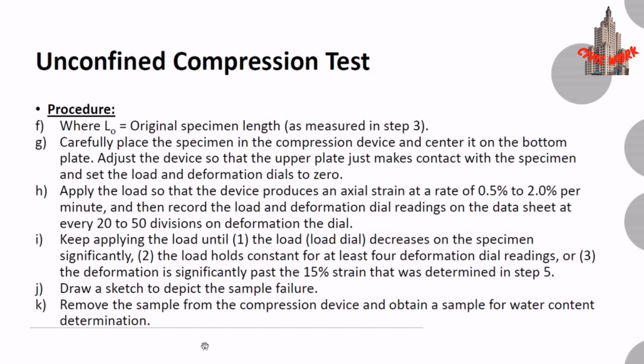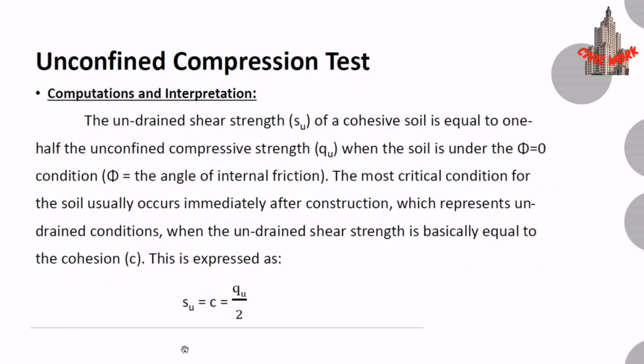Then we have to draw a sketch to depict the sample failure, which is between the stress strain, and then we have to remove the sample from the compression device and obtain a sample for water content determination. Computations and interpretation.